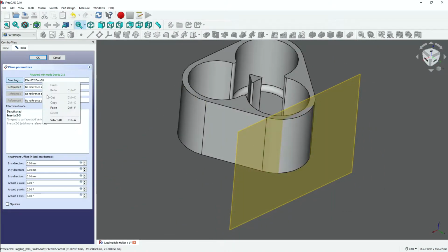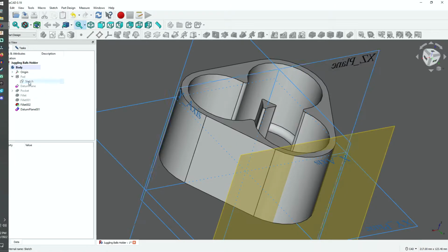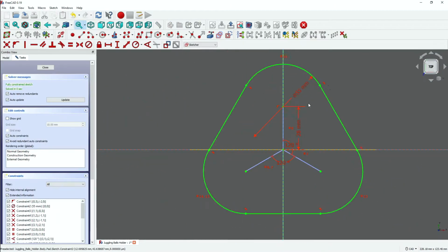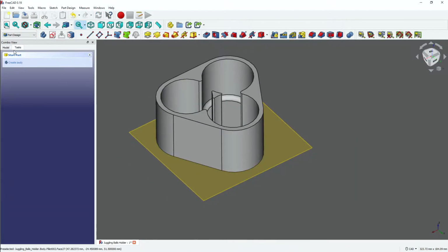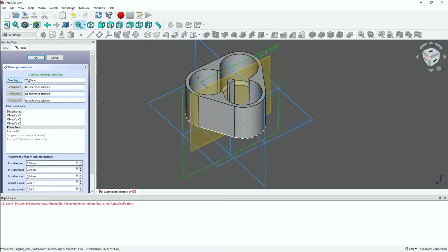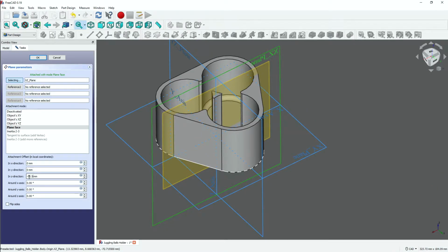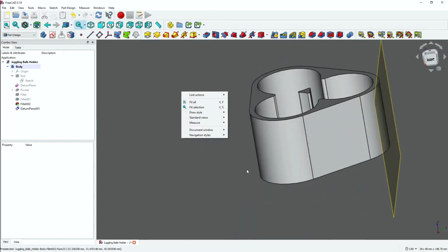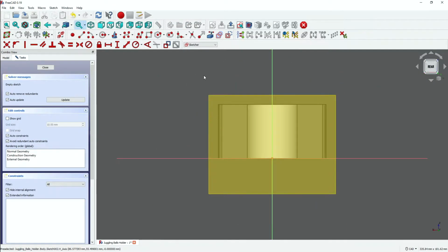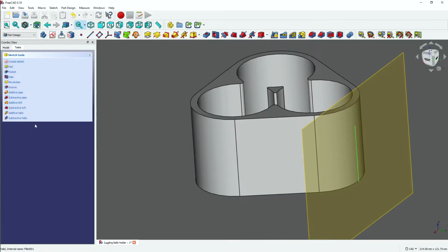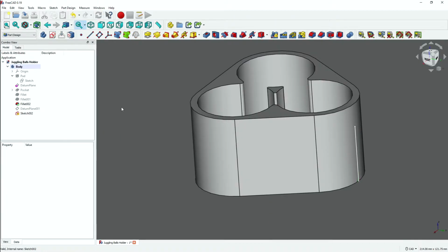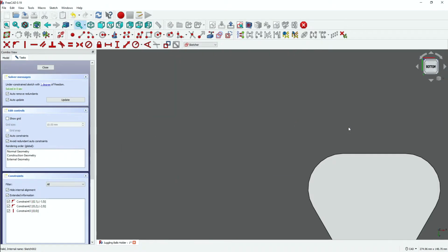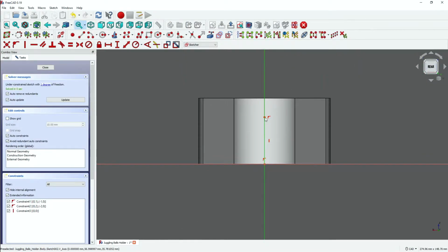So I actually wanted to figure out a way to make a hole on the side of this piece, which, to be fair, in other CAD softwares, it's a little bit difficult there too, to create a plane off a radius. But here I just basically made a datum plane that was offset from one of the main planes that we start with, and I just went past the arc, the body, because here it doesn't really matter. I'm not extruding, I'm actually cutting, or I'm not padding, I'm pocketing.